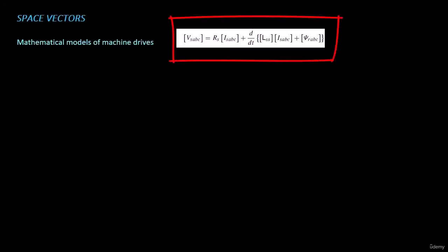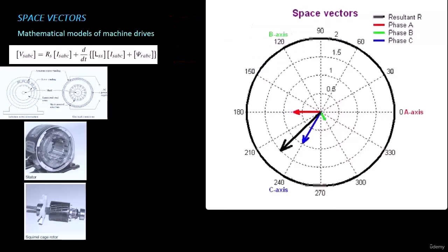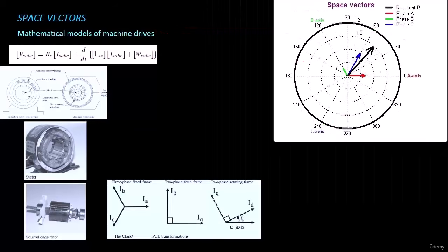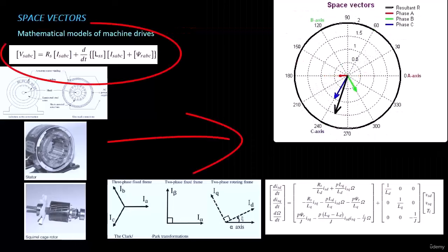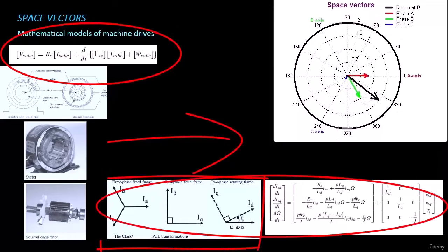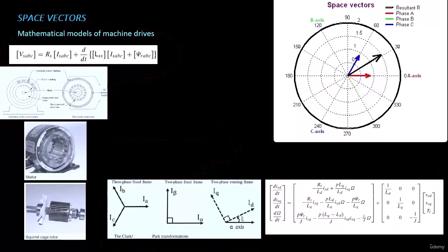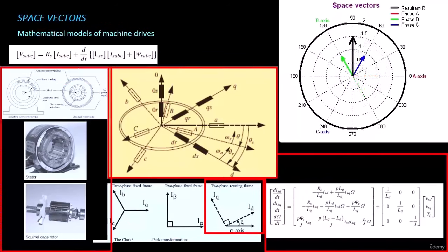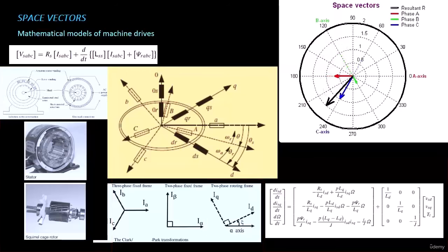Mathematical models of machine drives are derived in a uniform manner that first uses space vector description of physical variables such as voltage, current, and flux, and second transforms the space vector-based model into different frames of reference. By adopting this unified framework, it is hoped that the dynamic models of drives can be understood by a student who does not have extensive knowledge of AC machines due to derivation made in a similar process.